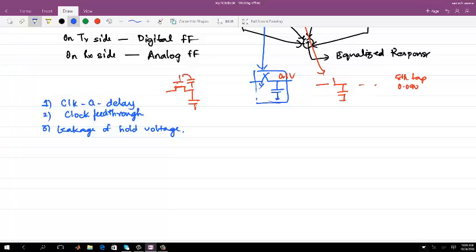Okay, so that means till now you have seen we have mostly dealt with the time domain waveforms. We have digital signals, we tried to explain in that manner. Less in the frequency domain, but they are equivalent. Not equal, they are the same, whether you consider time domain or frequency domain. But here when the signal becomes analog, it's difficult to talk in terms of digital signals. So we will start dealing with the signal as an analog signal and start dealing with the equalization in the frequency domain, where we consider how the equalizer frequency response is used to compensate the channel loss.